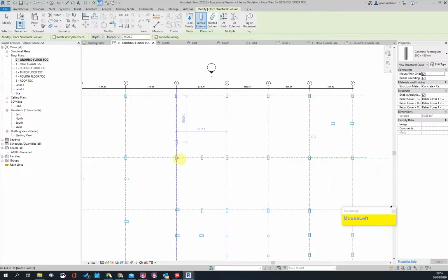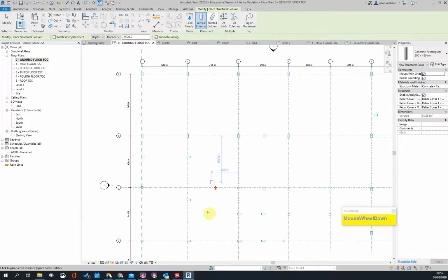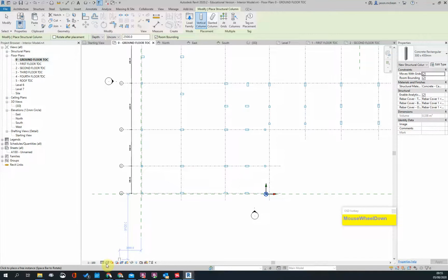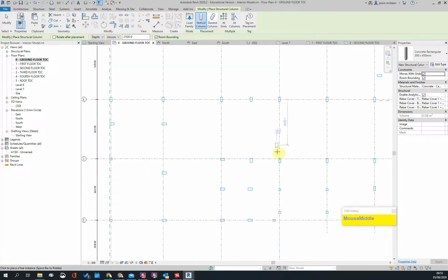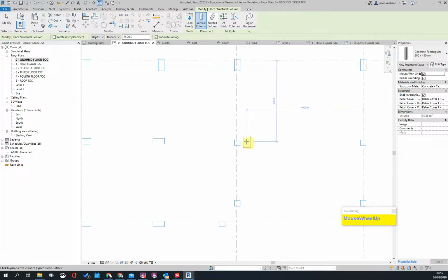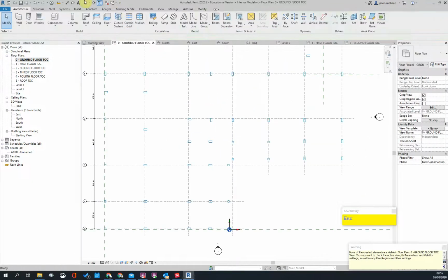Press OK. Here I've got a structural column for now, so I'm just going to put 2 in because you'll find that the sizes might differ, and I'm going to switch on visibility wireframe because if there's a discrepancy, I want to see it. So all I'm going to do is drop in, I've got a square one there, and I've got one, my mistake. Let me just do that again, 3D view.